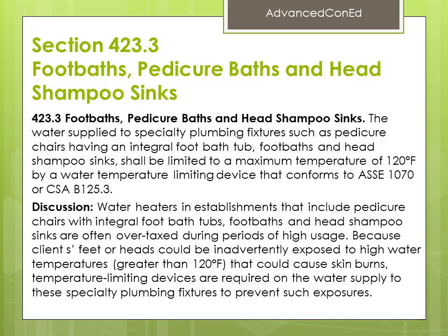Section 423.3 Foot baths, pedicure baths, and head shampoo sinks. 423.3 Foot baths, pedicure baths, and head shampoo sinks. The water supply to specialty plumbing fixtures, such as pedicure chairs having an integral foot bath tub, foot baths, and head shampoo sinks, shall be limited to a maximum temperature of 120 degrees Fahrenheit by a water temperature limiting device that conforms to ASSE 1070 or CSA B125.3.